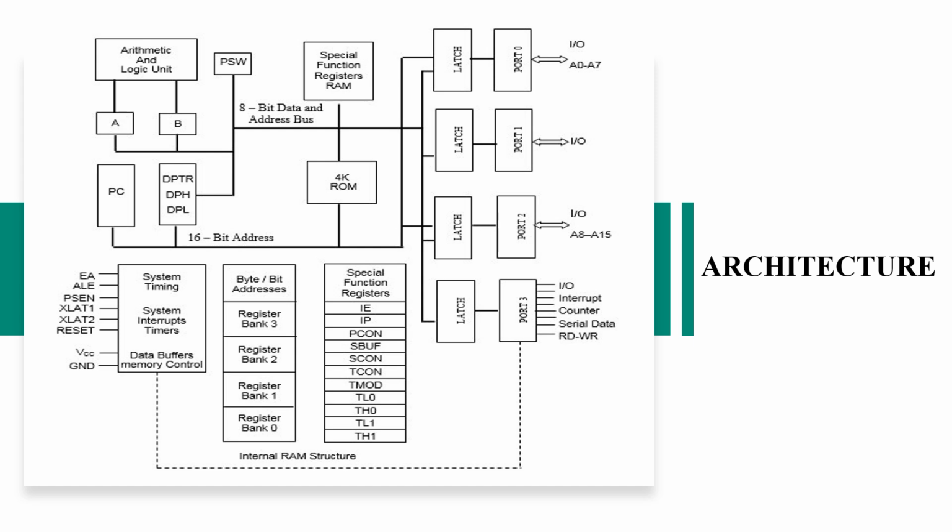There are some special function registers that you can see. Here is the memory unit and this is the special function registers. Special function registers are some on-chip memory locations where they can control various functionalities of the microcontroller. For example, the serial communication port or timers, counters, all these are controlled across the special function registers.